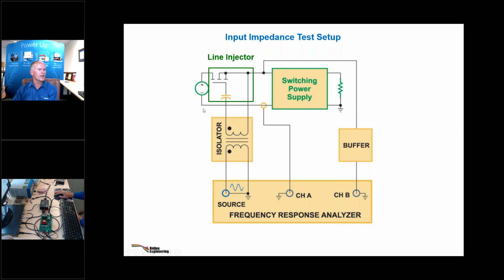How does the Middlebrook criteria apply? Yes, we'll get back to that one. Again, I want to do a webinar that talks about the undamped input filter, the Middlebrook criteria, and then how we can redesign the system and apparently violate the Middlebrook criteria, because that's becoming very important in high efficiency systems. Because efficiencies go up to 99% for some of these converters, you can't afford to damp the filter anymore. So if we can compensate the system without damping the filter, wouldn't that be cool? We can do that. Again, that was APEC last year that got canceled, so we'll do that again.